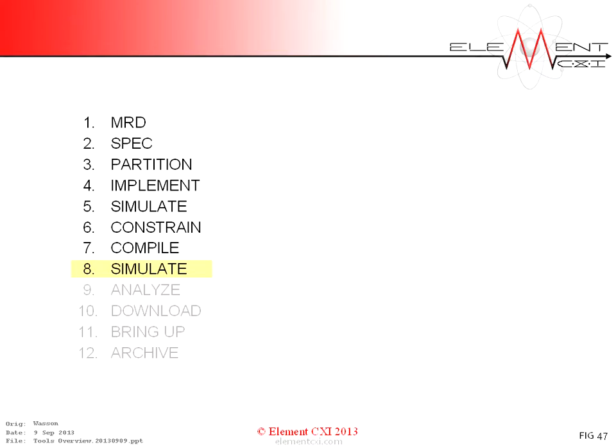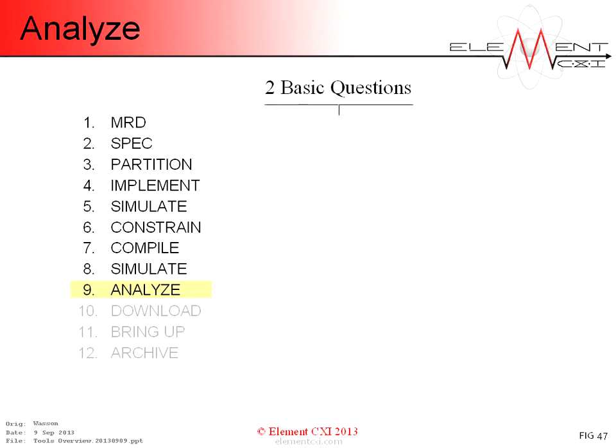After simulation, the next step is to analyze the design. Find out if it meets all user constraints. Analysis falls into two primary categories. Does it fit, and does it meet timing? Obviously, most fit analysis can and should be provided earlier. For example, final resource utilization is determinable after compilation. If the design is implemented with target-specific libraries, good resource estimates can be made during implementation.